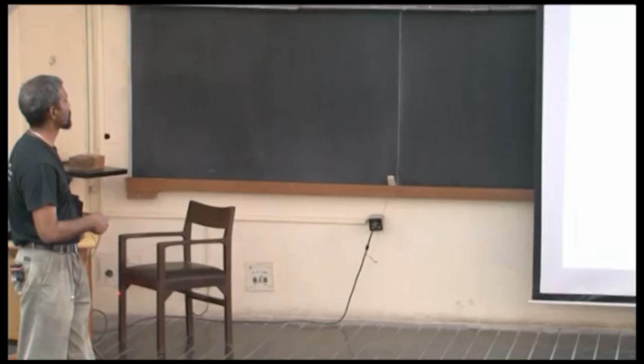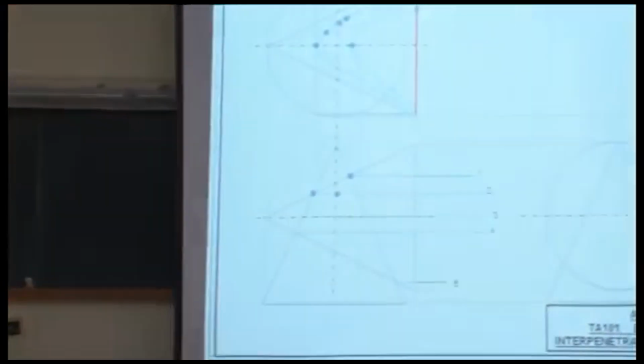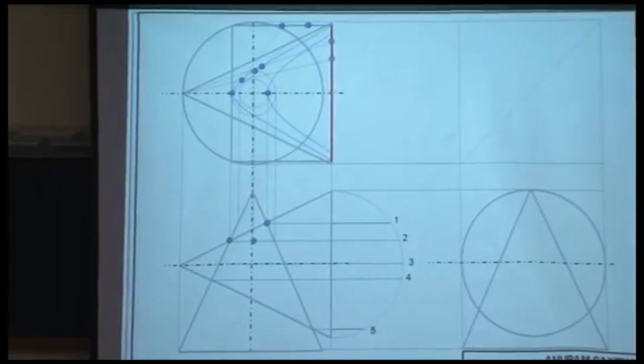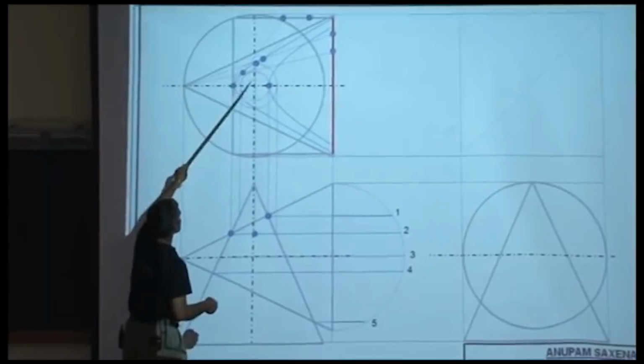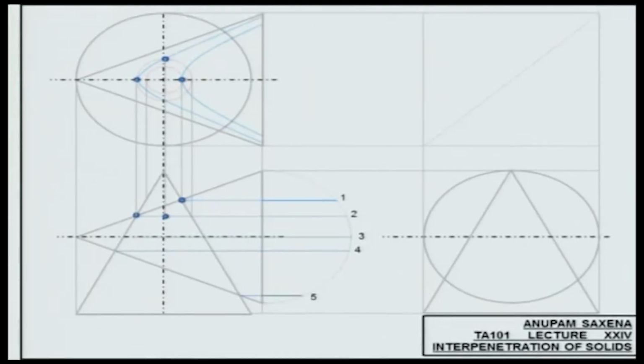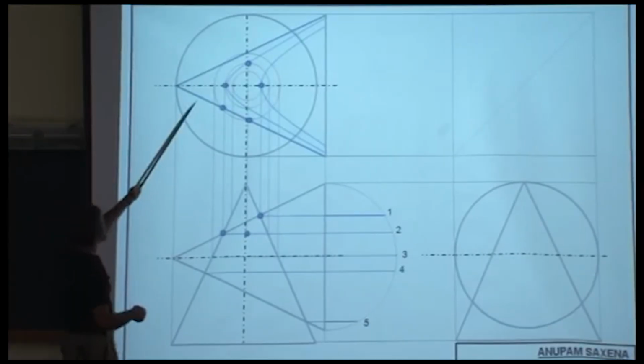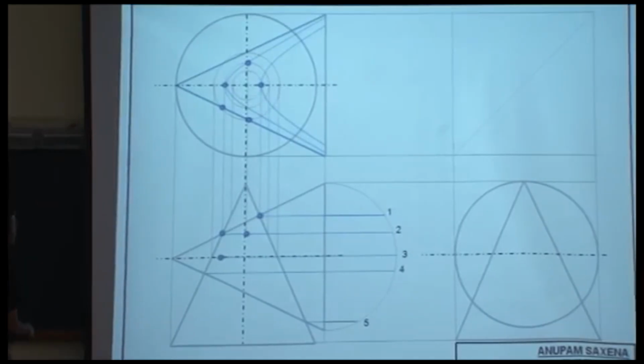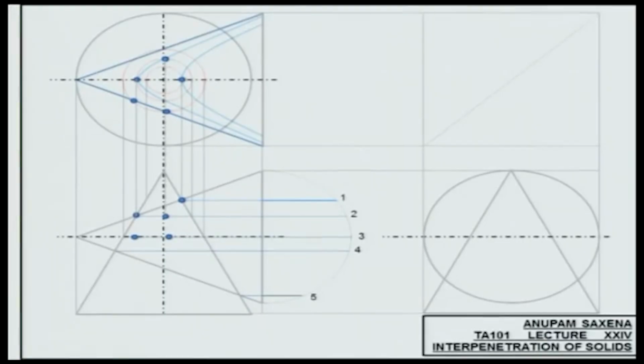This guy projected down onto the same plane. This guy projected down onto the same plane. So this would be one intersection point, 2 intersection points over here, and this one. Plane number 3 and the assembly. The vertical cone will give me a circle. The horizontal cone will give me kind of a triangle. So intersection points, getting that is not a problem. 2 intersection points over here and 2 intersection points over there being projected downward onto plane number 3. You'll get these 2 points.